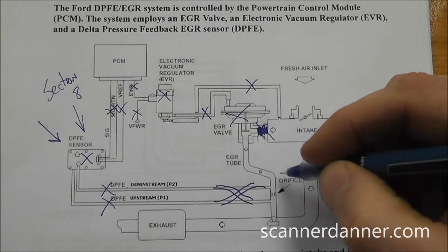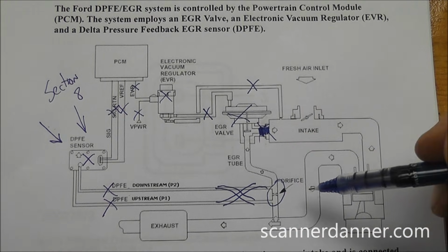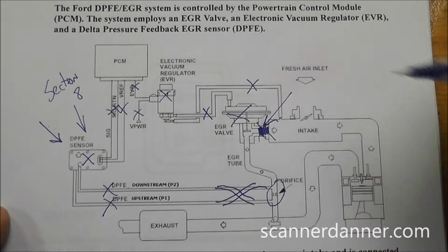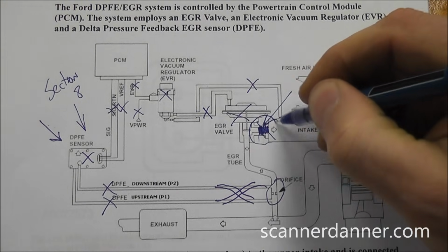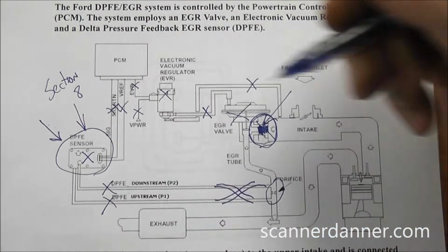Now some of you might be thinking, well, what about the tube and the orifice? And I have to tell you, I have never seen that orifice get restricted. It's on the exhaust side of the system. We don't build up carbon deposits on that side. Our carbon deposits are going to build up on the intake side where it rapidly cools, where it enters the intake. So a little bit unrelated to this video, but most of our EGR flow codes on Fords are going to be that side right there, that intake side of the EGR, or it's going to be this DPFE sensor.